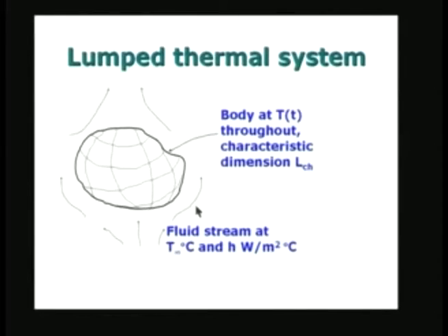Another way of visualizing the problem is, suppose the temperature T infinity is one value to start with, and suddenly there is some mechanism by which I change it. I want to find out what happens to the temperature indicated by sensor. It will be ideal if the sensor follows exactly what is happening to the temperature of the surrounding, which it is supposed to be measuring.